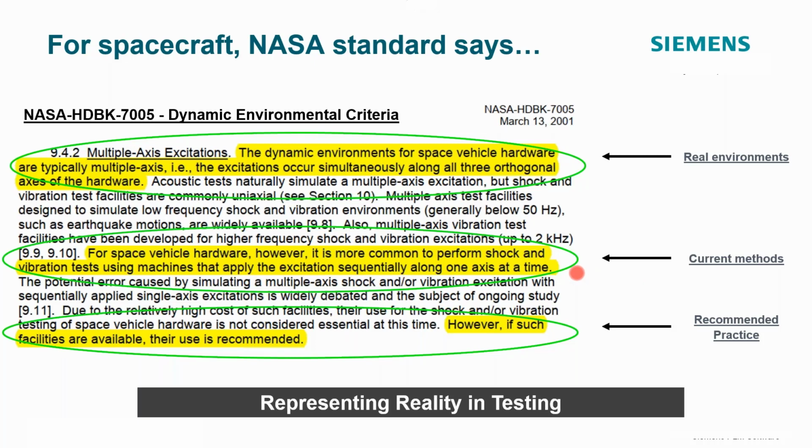And these tests would be done sequentially in three translational directions. However, they are recommending that if you do have the capability or can accommodate multi-directional testing, MIMO testing, then you should try to do that. And again, representing reality through testing.